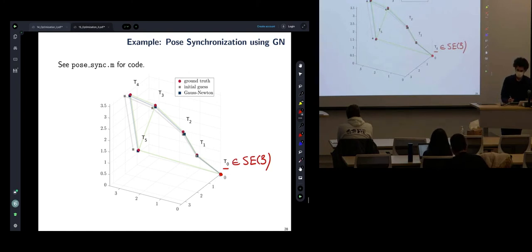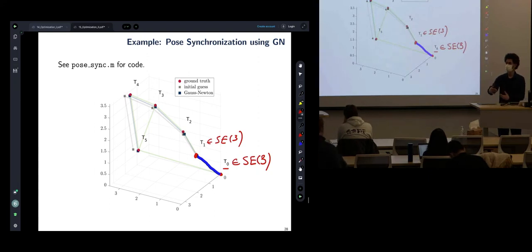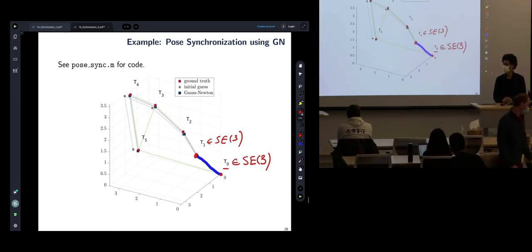We move and then we're at this point. How do you get this edge as an SE3 measurement? This can come from, for example, visual odometry, point cloud registration using LiDAR, maybe odometry, maybe you have a filter for state estimation. Somehow you can track the pose of the robot.